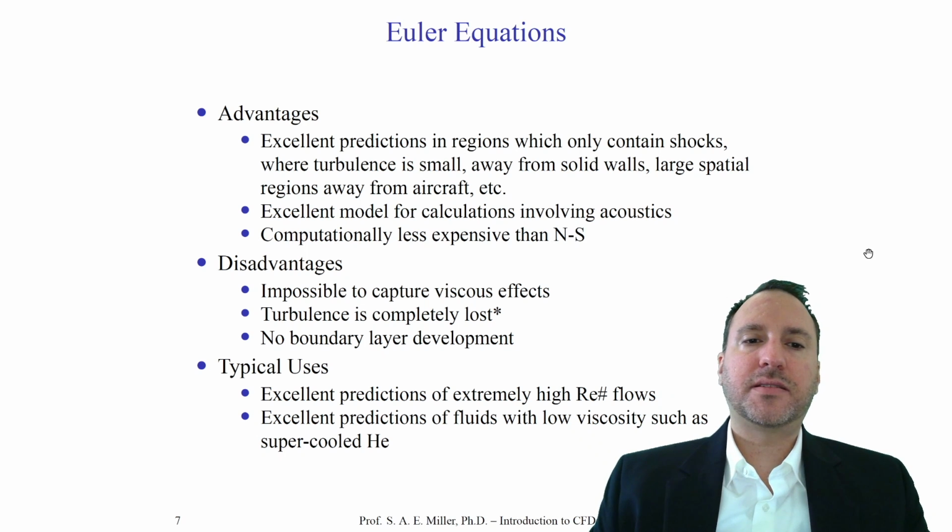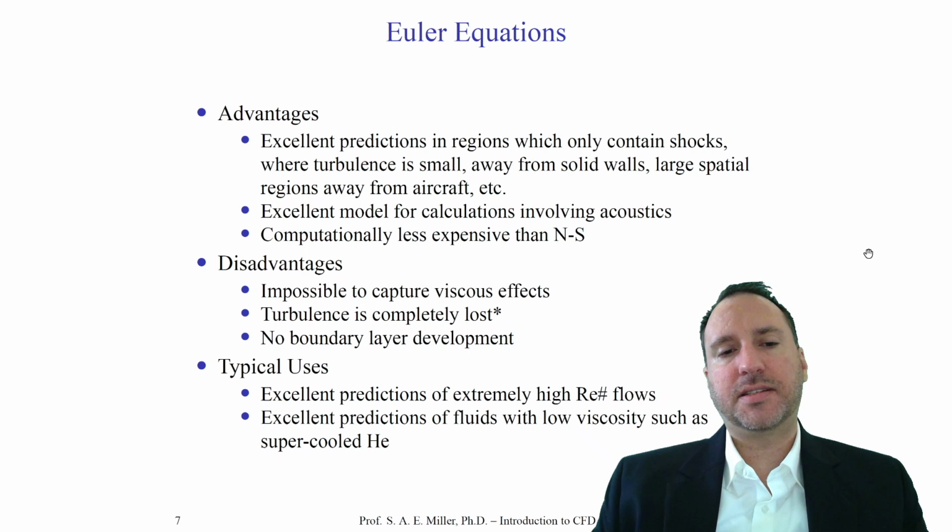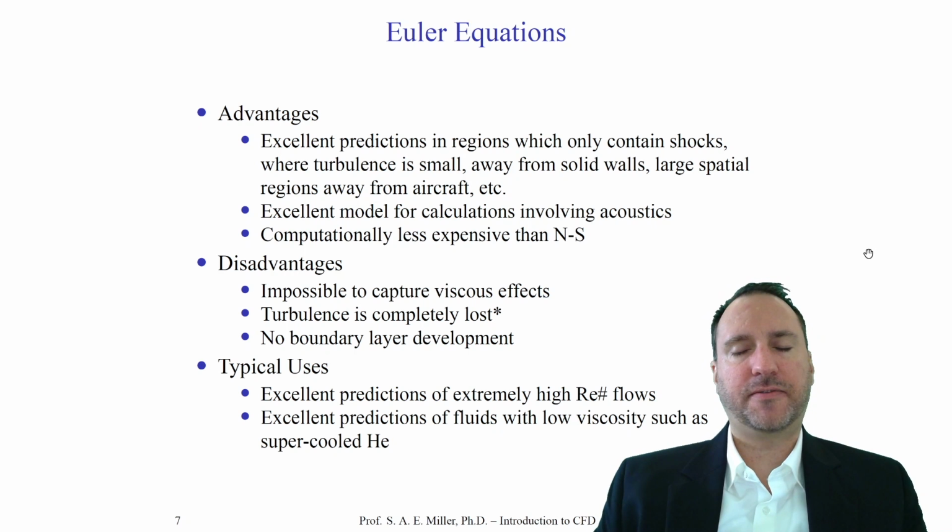Of course, making these assumptions, there's a price, and there are disadvantages. It is impossible to capture viscous effects because we have neglected the viscous effects. Therefore, the turbulence is completely lost. There is no true physical three-dimensional turbulence in the Euler equations. Also, there will be no boundary layers, and boundary layers are critical for calculating the true drag on a vehicle. You'll only be finding pressures on the boundaries, and you'll not be finding those shear stress terms that are due to the stresses from the viscous effects. However, this is okay in many situations, and we'll show one where it turns out to be a happy case.